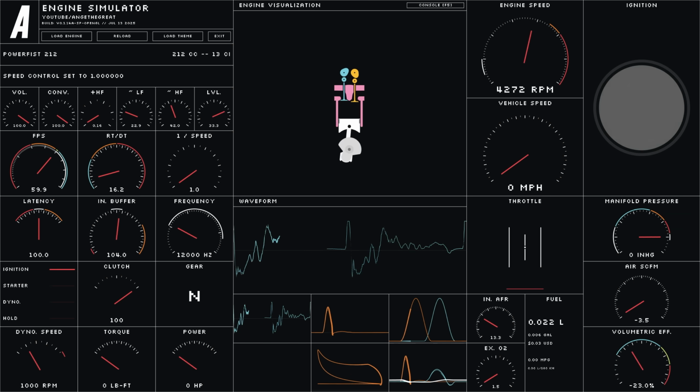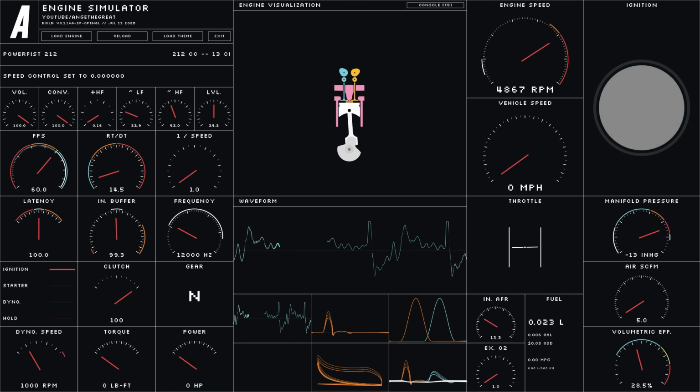I wouldn't say that it's that bad, especially considering how simple the simulation is, but the inaccuracies definitely show up most when the engine is idling and decelerating. Clearly, those are the conditions under which the gas dynamics in the exhaust become more important. This requires a more advanced fluid simulation to capture.